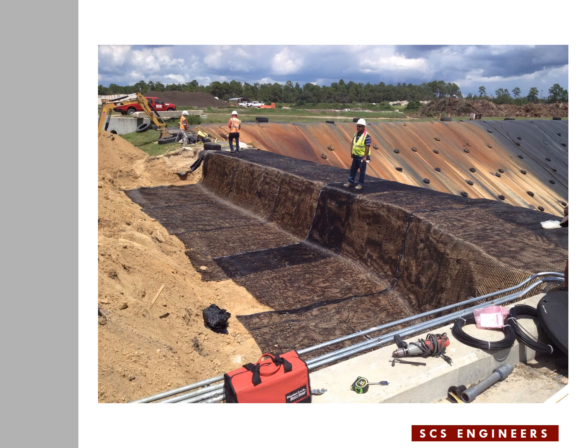At the top of the slope, geogrid goes into a larger anchor trench. This larger anchor trench is the one that was being formed in an earlier slide. A significant length of the geogrid is extended into the larger anchor trench for the purposes of increasing the surface area, contact area of geogrid with the backfill that's going to go over the geogrid in the anchor trench. The higher the surface area, the higher the holding capacity of the anchor trench.